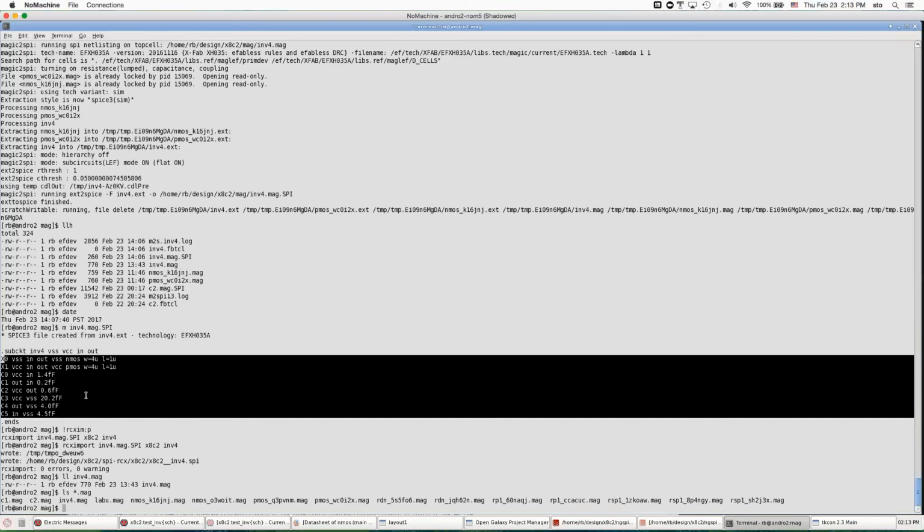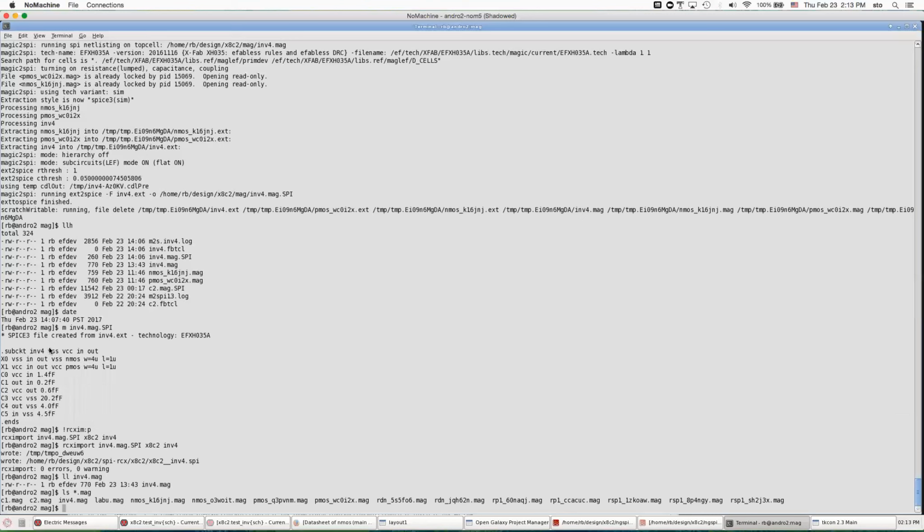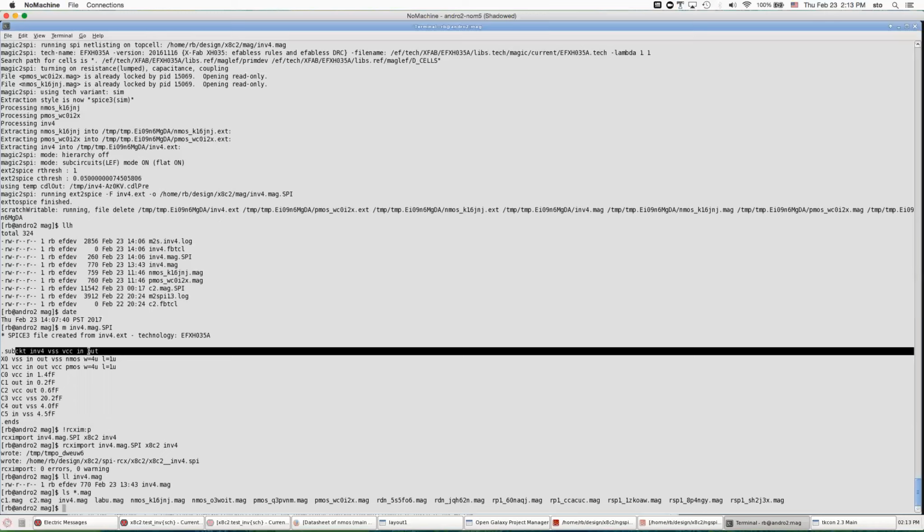So far, there's no requirement that structurally these two circuits are a match for each other. The only thing that's critical so far is that the pinout is a match. Otherwise, if you had insufficient pins, or pins in a different order, things would be really screwed up. You may get ngSpice complaining if you have a different number of pins.